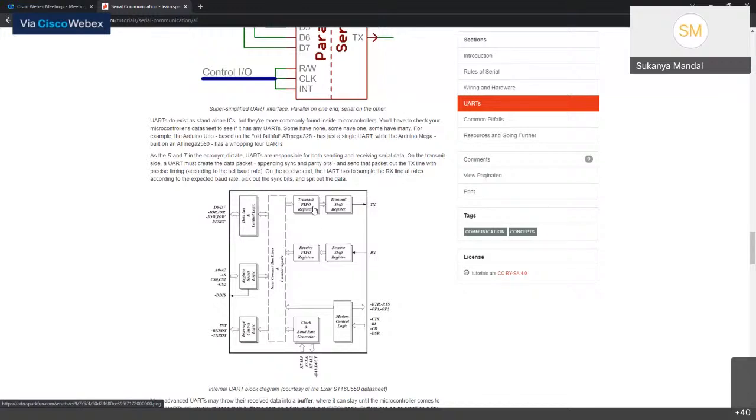Before buying, generally all versions of Arduino, since it's a microcontroller, have the UART RX and TX, but you could also read the data sheets. If you are going for other microcontrollers or microcomputers, like ESP8266 or, let's say, Samsung ARTIK or NVIDIA Jetson Nano, or simple MicroPython boards or other boards, just read the data sheet to understand what kind of pin configurations they have.